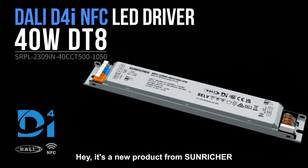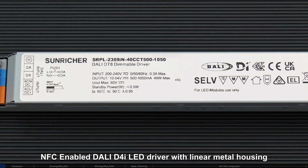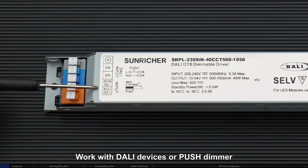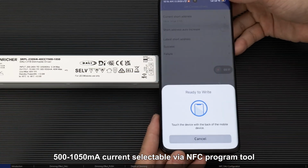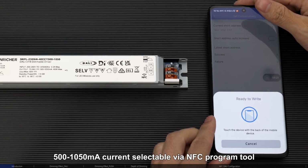Hey, it's a new product from Sunricher. NFC enabled DALI D4i LED driver with linear metal housing. Max output power 40 watts. Work with DALI devices or push dimmer. 500 to 1050 milliamperes current selectable via NFC program tool.